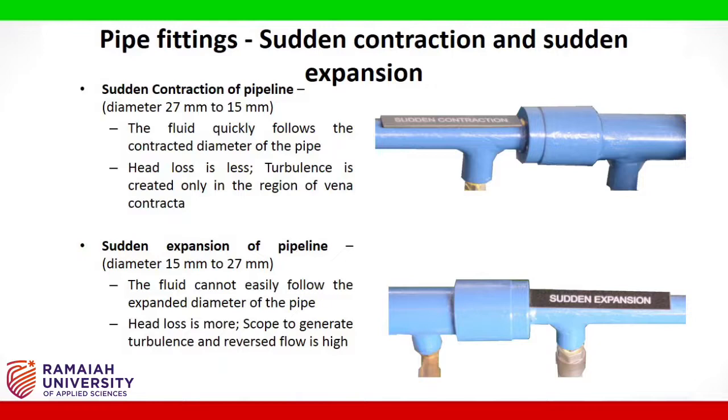Head loss is less and turbulence is created only in the region of vena contracta. A sudden expansion of the pipe from 15 mm to 27 mm is also installed. Here, the fluid cannot easily follow the expanded diameter of the pipe. Head loss is more and hence the scope to generate turbulence and reverse flow is high.